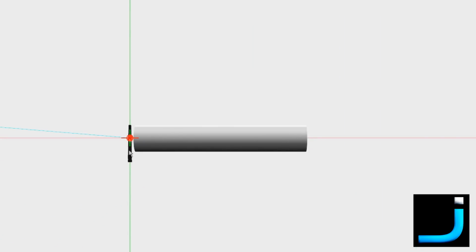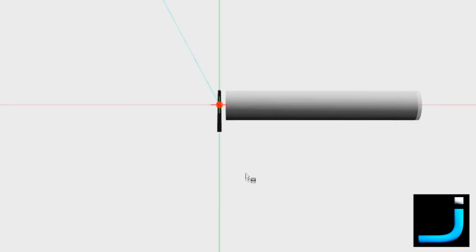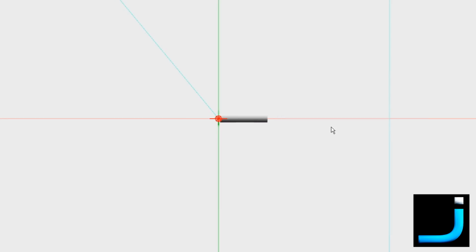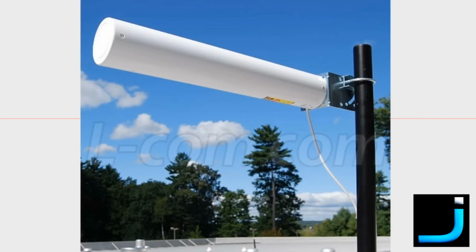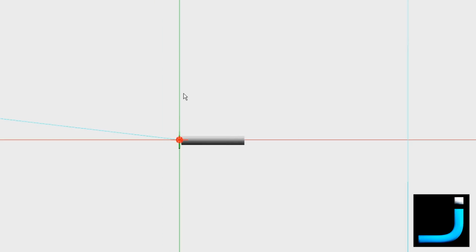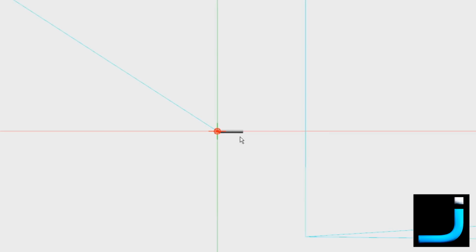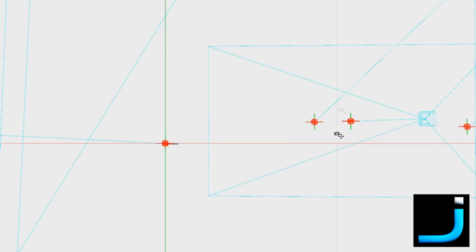If you compare that to your rubber ducky antenna, it's like a tube. These can be up to 2 meters long if you get extremely high gain. But we're going to base this on the 15 decibel Yagi antenna. So remember, the diversity was 11, the circular was 8, and the rubber ducky is 2. So this is your Yagi, which is 15 decibel, which is about half a meter long. Let's have a look at the pattern for a Yagi.